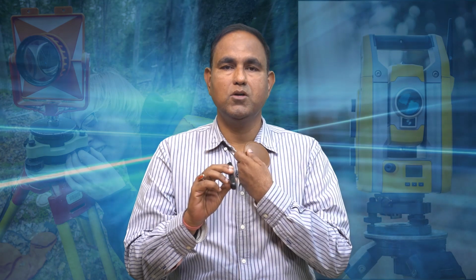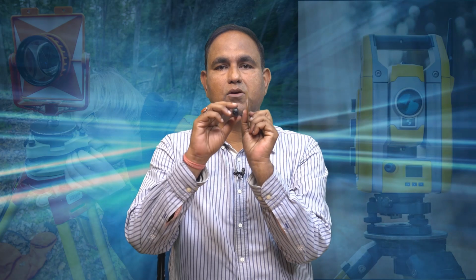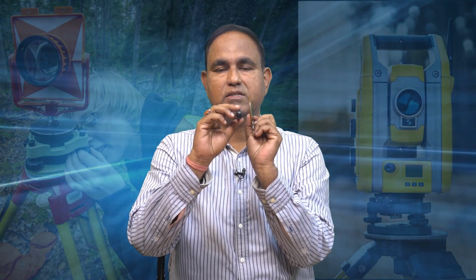Again look, this is the telescope, this is the observer, and this is the vertical circle. So, if the vertical circle is on the left of the observer, this setting is called face left, and if the vertical circle is on the right side of the observer or right side of the telescope, this reading would be designated as face right readings. Some of the terms may be confusing, but with a little practice and consideration it will be easy.